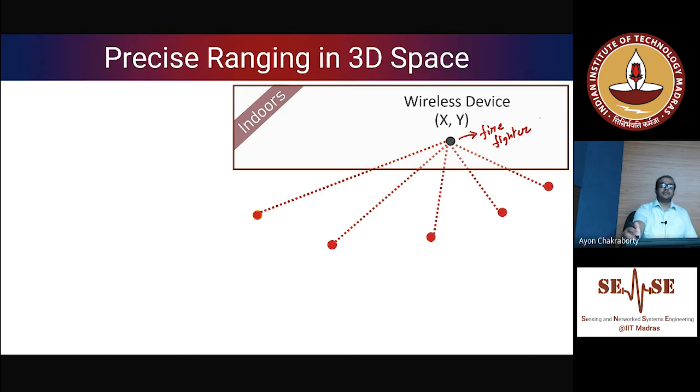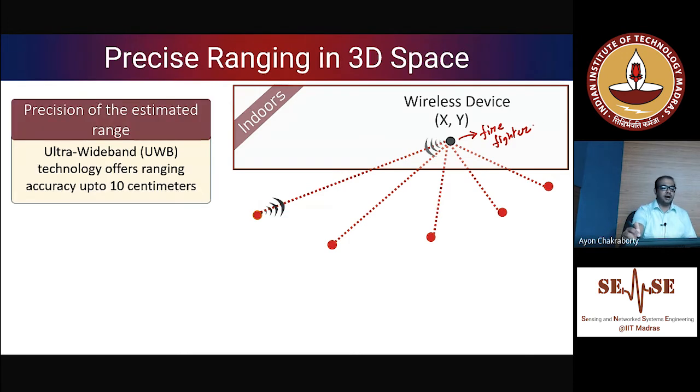Okay, so the first part is that we use ultra wideband, which is going to give you a very good distance resolution as well as good accuracy. The accuracy could be in centimeters, and we have already seen that the precision can reach millimeters, because it is tens of picoseconds time resolution in the impulse response.